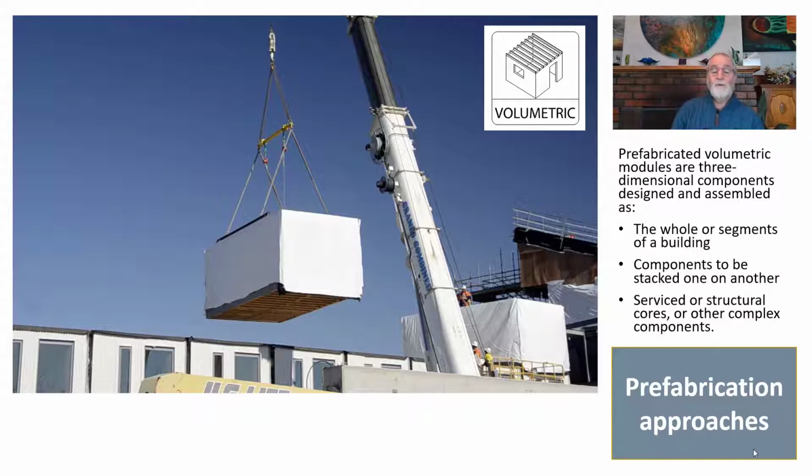What we're seeing here in this photograph is that these are university accommodation modules. So each one of those is a student apartment. It's manufactured off-site, brought to site, and then stacked one on top of the other. They're load-bearing objects to form the basis of the building. And they're completely finished. So the services are all in place, the plumbing's in place, the tiling and joinery are all in.